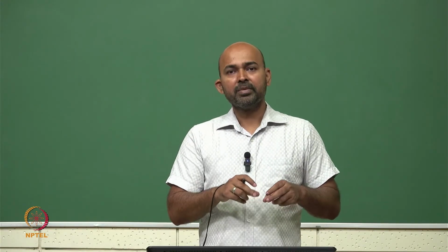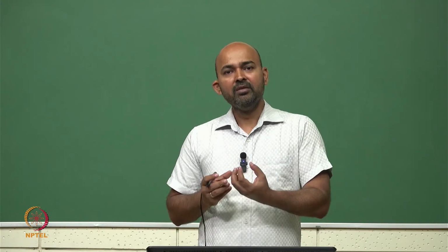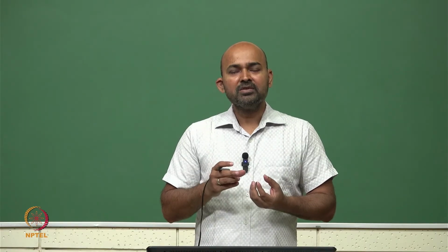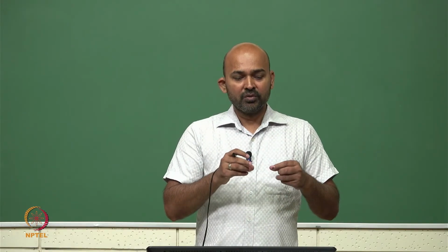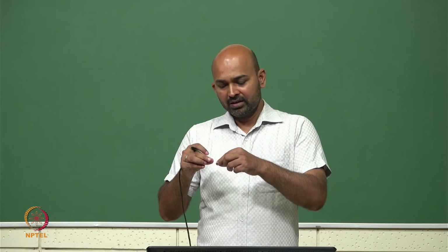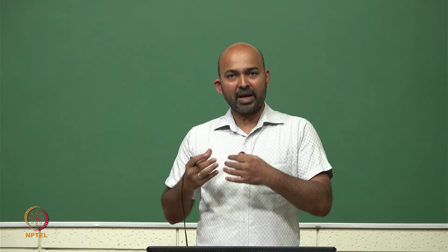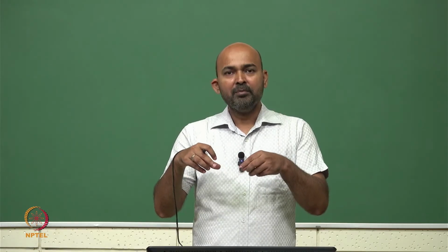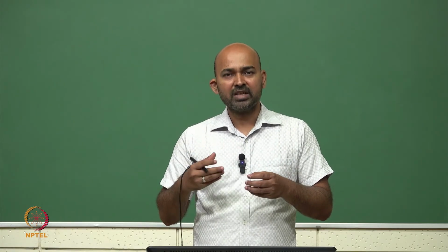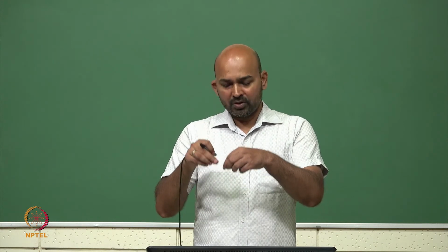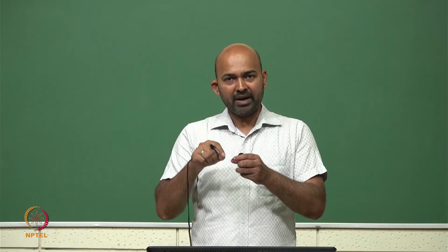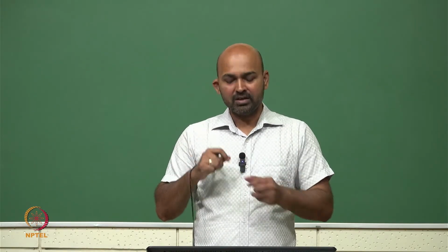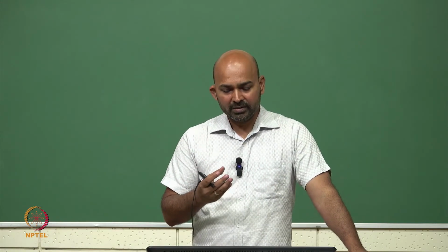So once we have this IC, this chip fabricated by the foundry, this will be delivered to us. Then this chip is very fragile. We cannot even touch it with bare hands. So we take this chip and put it in a protective enclosure which is called the package. The package is a metallic casing usually made up of ceramics. We put this chip on the package and we connect the outer periphery, the pads on the chip, to the pins of the package. So these packages provide multiple functions.